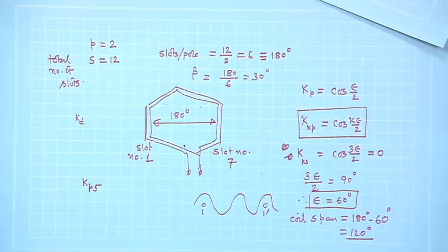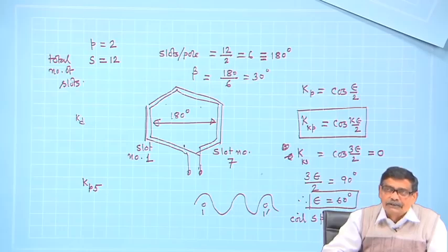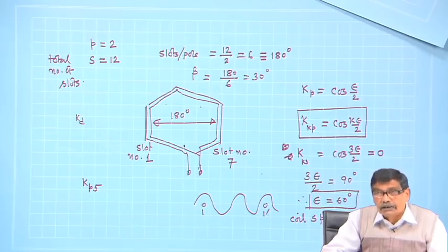We will see in a 3-phase machine, line to line voltage, even if third harmonic voltages are present in the coils, they do not appear in the line to line voltage. So maybe at that time you will be interested to see that okay, fifth harmonic voltage I will try to nullify to 0.